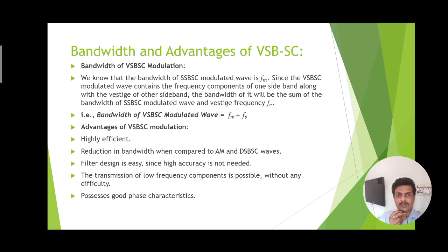So this is one of the disadvantages of VSB-SC compared to SSB-SC, though SSB-SC has a more difficult situation. That is, if a sharp cutoff filter is utilized, then important information, for which no compensation technique is utilized, may be suppressed. But here a compensation is made by the vestige of the other sideband. So that is a great advantage over the small disadvantage of a little bit higher spectrum. Higher spectrum means a little bit more money you have to pay to occupy the channel.